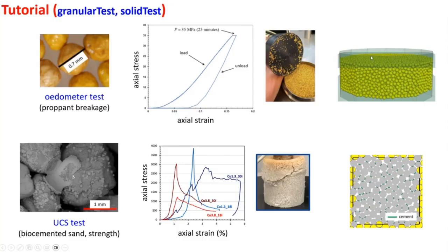Then they inject a fluid that has certain bacteria in it, and they slowly pump the fluid up through this for about, I think, 8 hours. And then that produces a chemical reaction that makes calcium carbonate form, which ends up acting like a cement. And they call this biocemented sand.